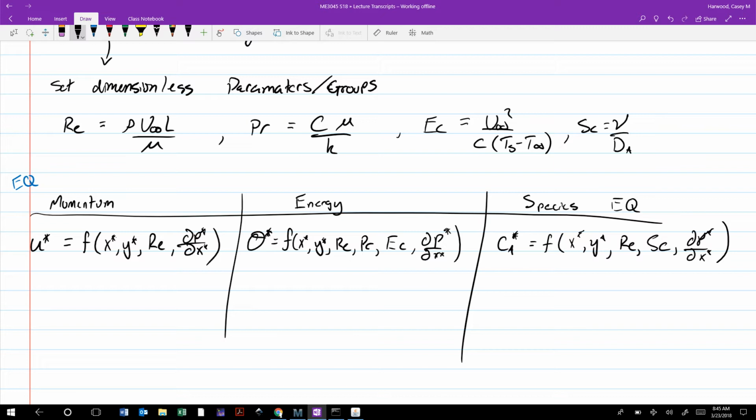So that's going to be a function of the temperature, namely through the use of this thing called the Nusselt number, which is defined as hL over the fluid conductivity, which is also defined as the dimensionless rate of change of the temperature at the surface.